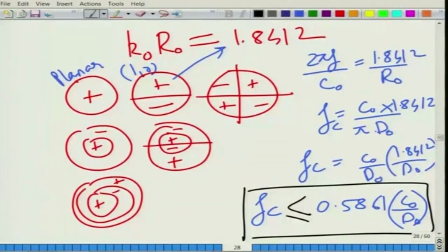But the idea is to find out the propagation frequency of the lowest order mode and then check if you are above or below that frequency. If you are below, then the transfer matrix for a uniform tube will apply. Now, quickly getting back to our topic, I guess we digressed quite a bit, but that was important.